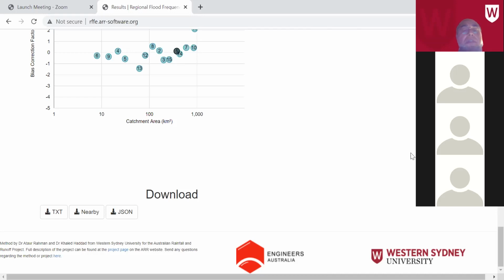So when we put the data, it automatically selects the nearby catchments, right? Yeah. Is there any threshold for how many catchments it might select, or is it based on the region of homogeneity? It's doing some optimization. It starts with, say, 5 catchments and then it increases, and checks whether 5 is not very good, then 10, 20, 50, and does a kind of optimization. It takes the optimum value when the error is minimum with size.